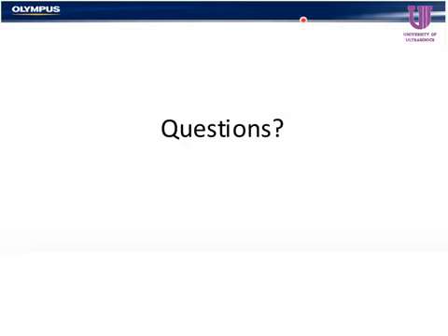A couple of questions that I got through. One was, is scan planning required for other materials or other applications? Scan planning, you end up performing really regardless of the type of material or the type of application. So it's always important in a phased array inspection that you address some form of a scan plan. So do you have a different type of material, or it's not a weld? Yes, scan planning is important.